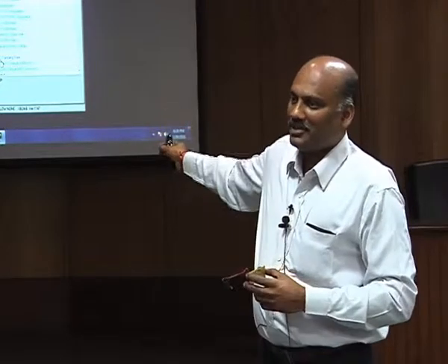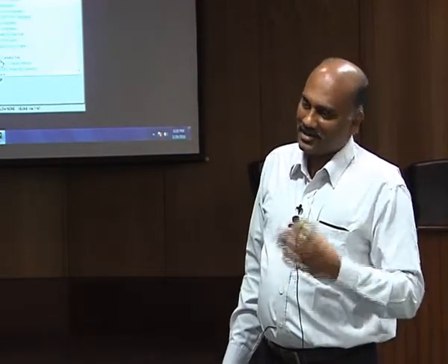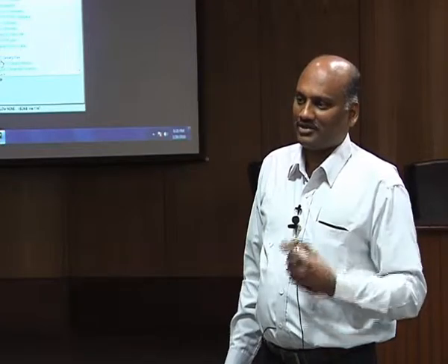One thing more, while configuring this: because this is not a coordinator, I have to connect this to this. That is what I am going to show you, ma'am. You have to pop it out, use the same explorer and push back the other XBee, so that you make it a device end. The configuration values will differ. The same chip can be configured as a coordinator and also as a sensor, a device end or a router, but the parameters will be different.